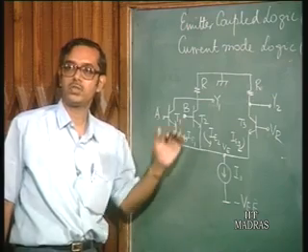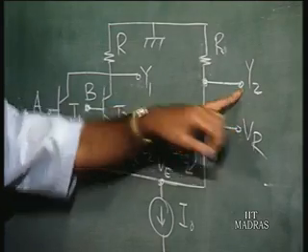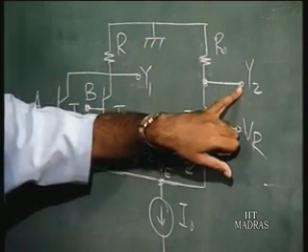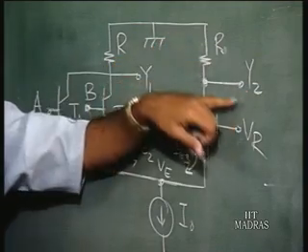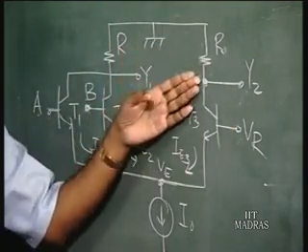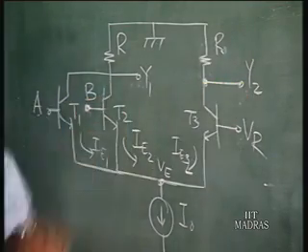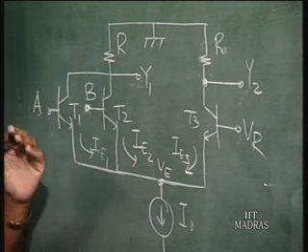Output voltage is going to change from... so if you take the output from Y2, when no current is flowing in this branch, the output is equal to 0. The voltage here is 0, it is ground voltage. And when the entire I naught is flowing in this branch, the voltage is minus V on. So the output voltage at any output is varying from 0 to minus V on.